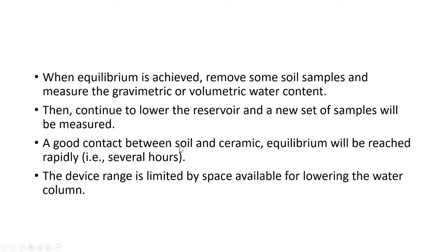With good contact between soil and ceramic, equilibrium will be reached rapidly. That is, we have to wait for several hours for equilibrium to be achieved before we can take out the soil sample to measure the soil water content. So the device range is limited by the space available for lowering the water column.